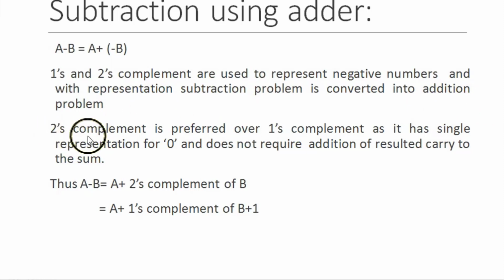It should be noted that 2's complement is preferred over 1's complement in implementations as it has a single representation for 0 and it does not require addition of the resultant carry to the sum. Thus, A minus B can be said as A plus 2's complement of B,